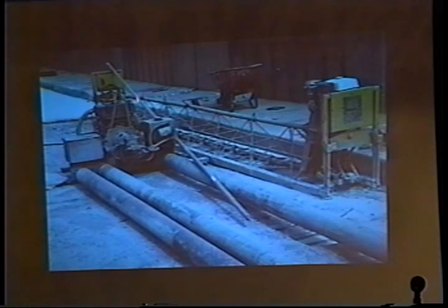Here's some other commercially available screeds. This is a fairly typical truss type vibrating screed now. You can get those gasoline powered, you can get them air powered and electric. So they're available in 3 different choices. This is a more heavy duty roller, vibrating roller type screed. You probably wouldn't want to use something like that on small repairs in a local community.